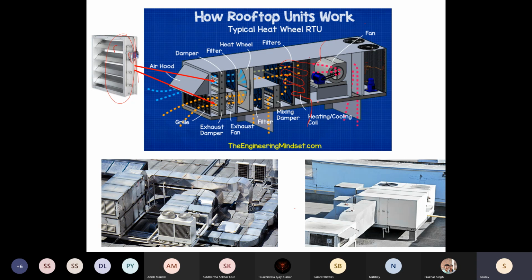And it supplies cold water to the rooftop unit. Now the rooftop unit has to take only the load of the ducting and the dampers and filters and all, which is pretty light, instead of taking the entire static weight of the refrigeration system as well as vibrational load. So the roof need not be very strong if you have your refrigeration system outside.